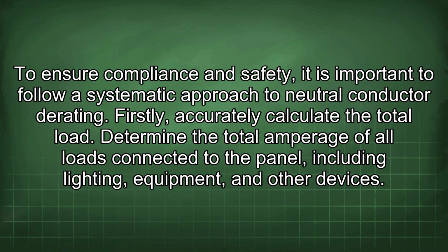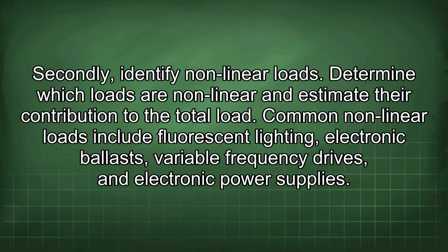To ensure compliance and safety, it is important to follow a systematic approach to neutral conductor derating. Firstly, accurately calculate the total load. Determine the total amperage of all loads connected to the panel, including lighting, equipment, and other devices. Secondly, identify nonlinear loads. Determine which loads are nonlinear and estimate their contribution to the total load. Common nonlinear loads include fluorescent lighting, electronic ballast, variable frequency drives, and electronic power supplies.